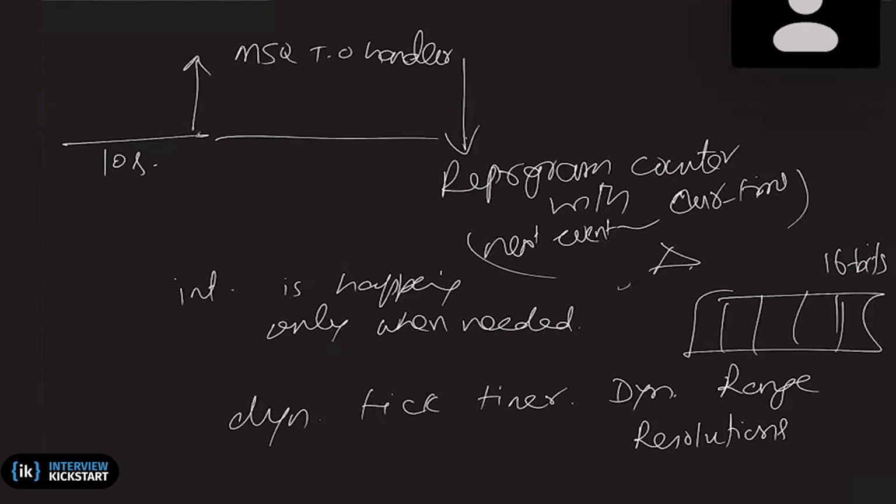So this is basically the idea. And obviously the benefits are basically less power consumption, because you are waking up only when there is a real event. Now there is complexity to this. This is why it is not very commonly used, because you need to keep track of all the events. Suppose a new event is scheduled, let's say another task is waiting on a semaphore, again with a timed wait. Then you have to insert a new timer value.